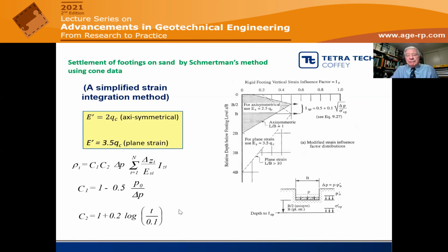And you've got a couple of modification factors for stress level and also for time, because there is generally a time effect with settlement of footings on sand.